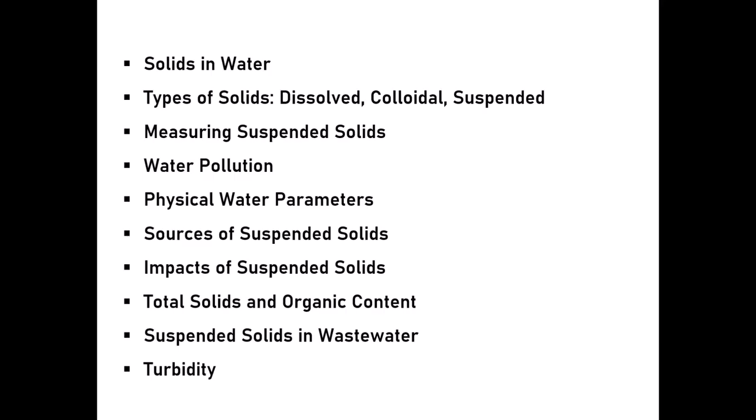Finally, turbidity measures how much light is scattered or absorbed by particles in water, caused mostly by fine suspended solids, not just the total amount of solids. Turbid water is visually displeasing and can interfere with disinfection. Sources include clay, silt, organic matter, and chemicals like detergents.